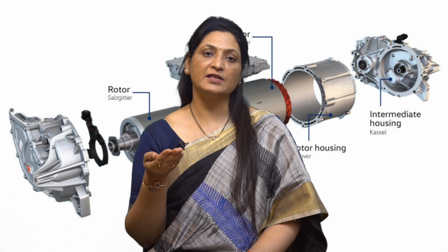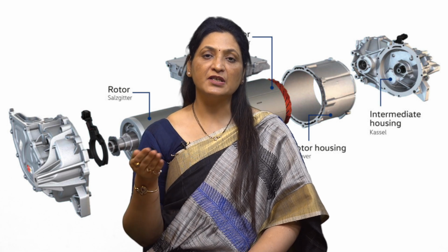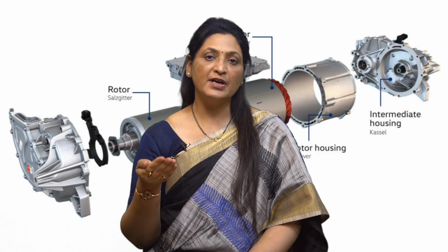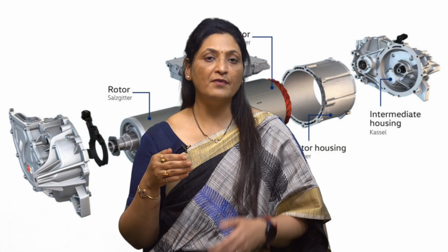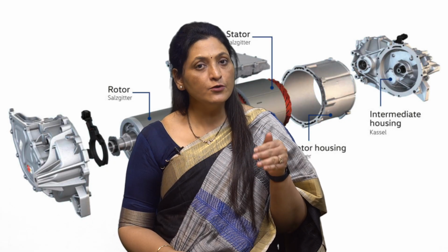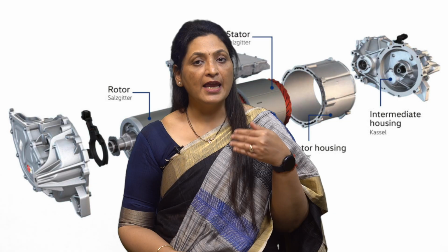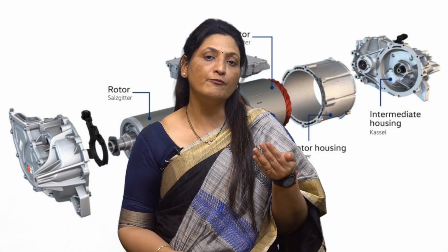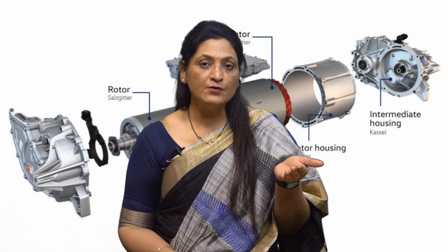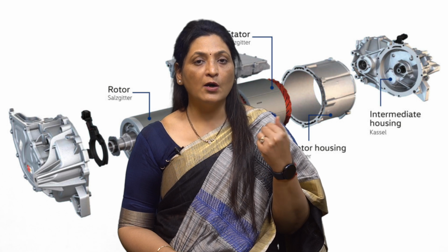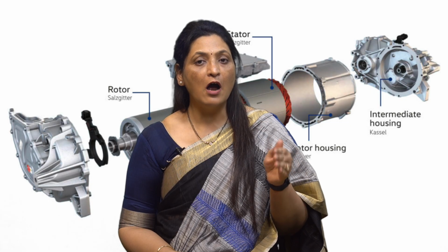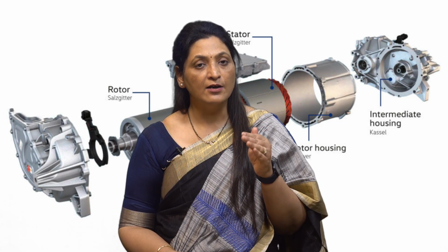Now, what is this load equalization? In many industrial drives such as in rolling mills, planing machines, electric hammers, presses, reciprocating pumps, the load fluctuates over a wide range in the space of a few seconds. So, it is desirable to smoothen out the fluctuations in load, otherwise during the interval of peak load it will draw very heavy current from the supply, producing large voltage drop in the distribution system and requiring cables and wires of heavy section. The process of smoothing out the fluctuations in the load is known as load equalization.